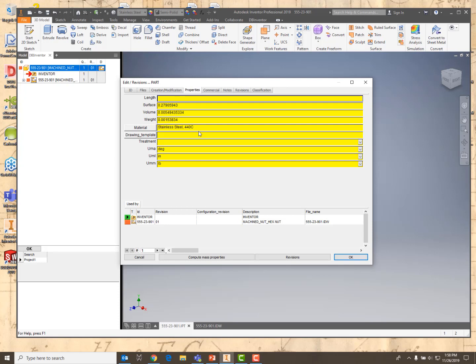With many of the entries that you might want for your properties, within your organization, you may want it to all be uppercase. So what you can do with the MechWorks PDM is it can be configured so that no matter how it's entered, it will always be uppercase. So if we go into here and we enter brushed in lowercase, you'll notice that it automatically goes into uppercase.